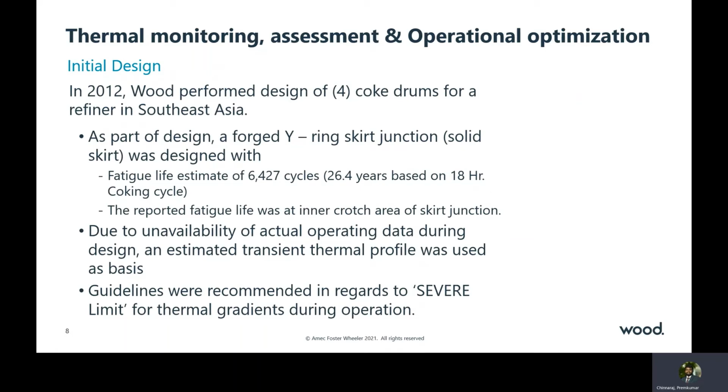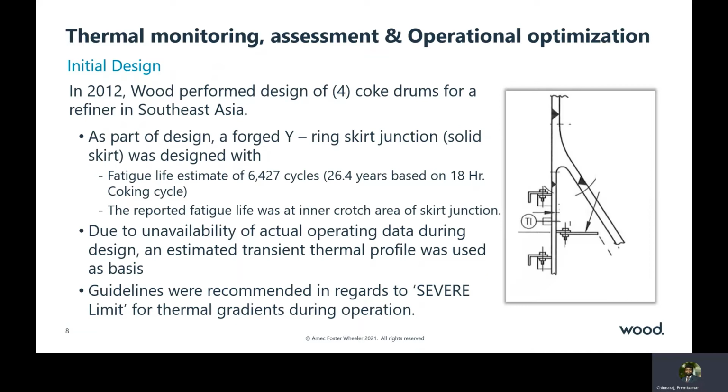Finite element analysis was performed to optimize the skirt geometry, and the resulting fatigue life estimate at the inner crotch area was approximately 6,500 cycles. During the design phase, there was no actual operating data from the field. Therefore, an estimated transient thermal profile was developed based on experience with similar operating units. Later, thermal guidelines were provided to the operator to monitor the severity of gradients and temperature differential during operation.